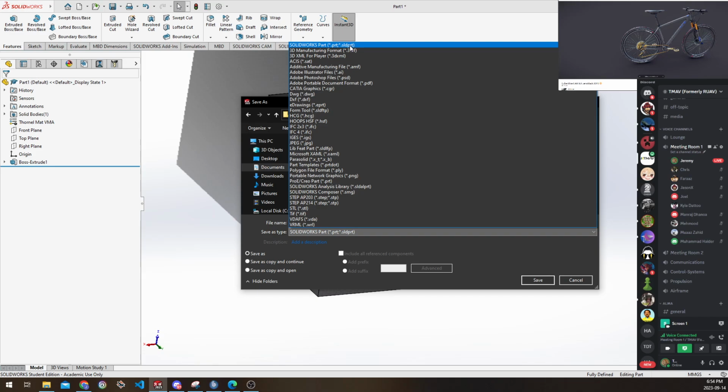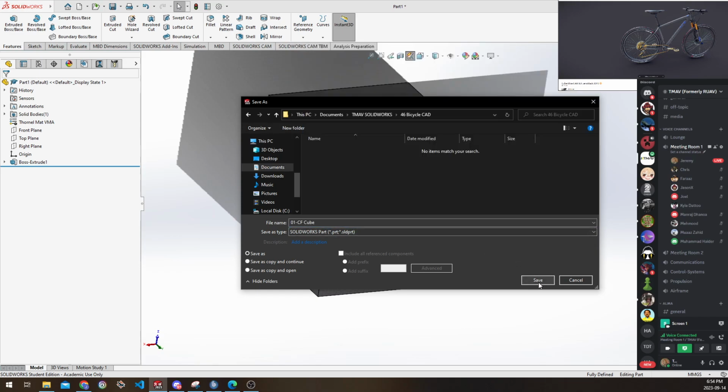So whenever I share a CAD with him, I export this as step so that he can open it in Fusion 360. SolidWorks he will not be able to open, he will not be able to convert on his own. He'll have to send it to me to convert for him, okay? Just keep in mind that it can also be useful to export your files as step. The only thing you have to remember is you can never take it from step back into a part. You lose information when you make that change, okay? So just keep that in mind as well.